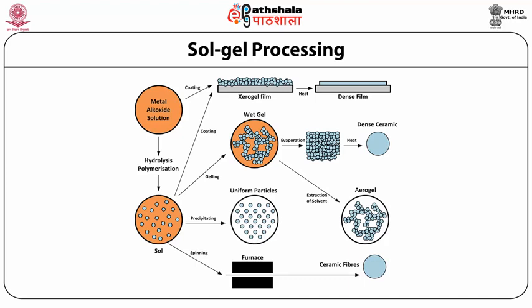The sol-gel approach is a cheap and low temperature technique that allows for the fine control of the product's chemical composition. Even small quantities of dopants such as organic dyes and rare earth elements can be introduced in the sol and end up uniformly dispersed in the final product.